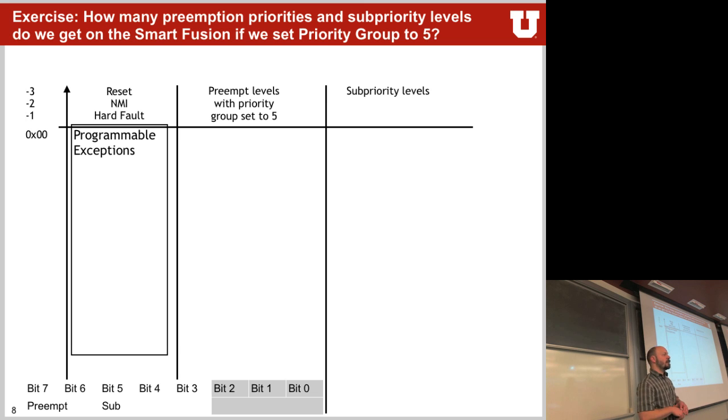It turns out that a vendor does not have to implement all priority levels, because that generates a lot of logic in the background. So oftentimes they opt for fewer bits. Then the lower bits are just static zeros, and only the upper bits get used for the different priorities. In this case, we have 5 bits in the top and 3 bits at the bottom. These 3 bits will never be changed, and these we can use for programmability.